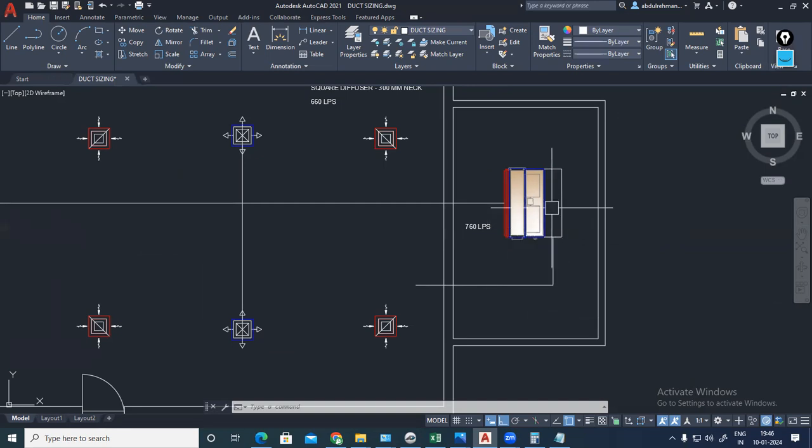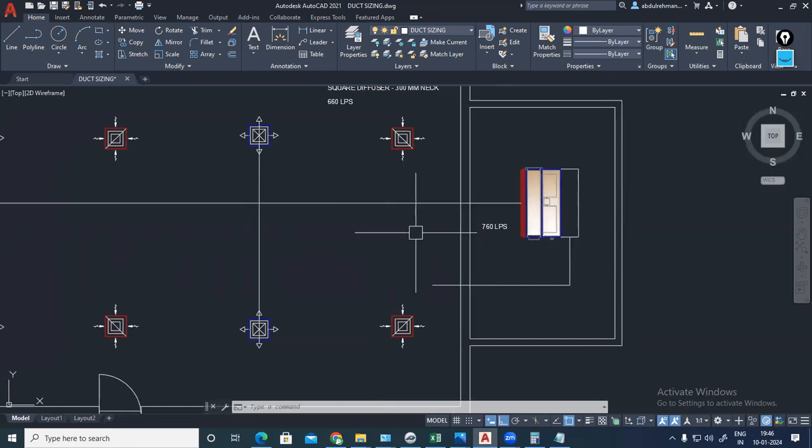And this is written only since the machine is located outside the space it is serving. If this machine is located inside here, a return duct is not mandatory. But since it is located outside, a return path has to be arranged. We can discuss that. Anyhow, let me mark the airflow rate.